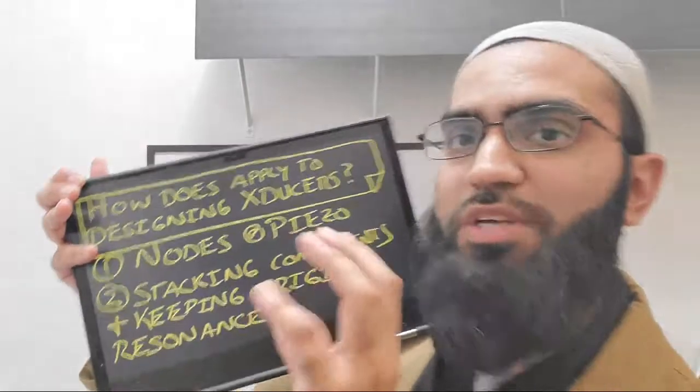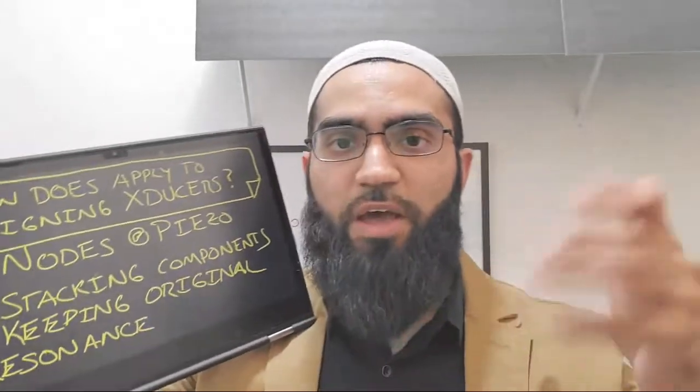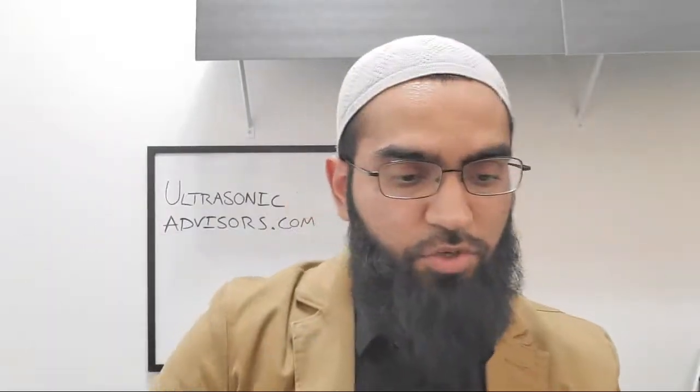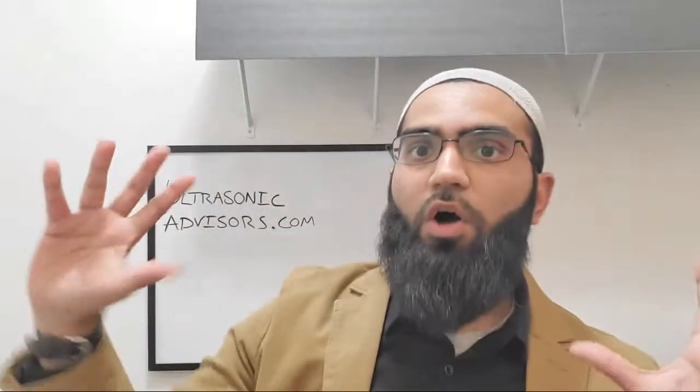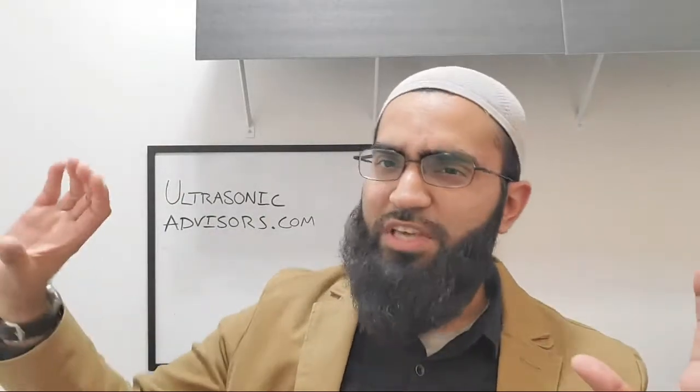The next is when you assemble multiple components together. In many cases you have a transducer, and then you screw on and attach other tools, other horns, to that mechanism. And the wavelength of those tools needs to match the wavelength that you optimized your transducer for. So your transducer still operates in the same mode shape, it has a maximum displacement at the same point, and it has the node points right where you designed it for your piezo. They all work together in the same way, even though you just attach this big tool.